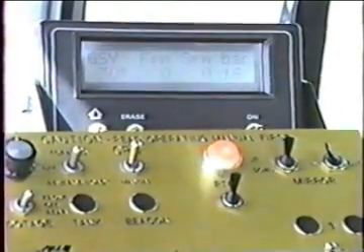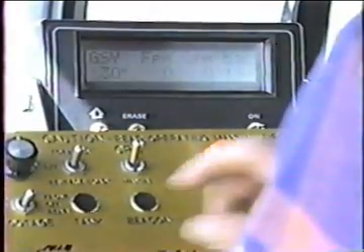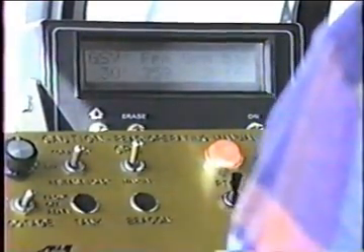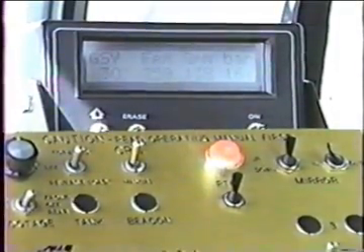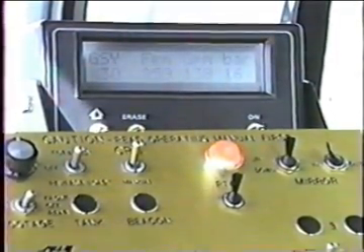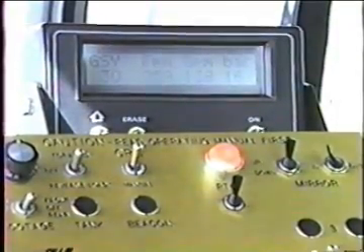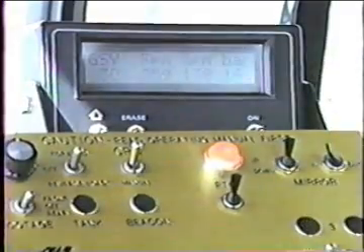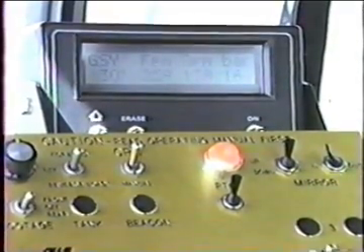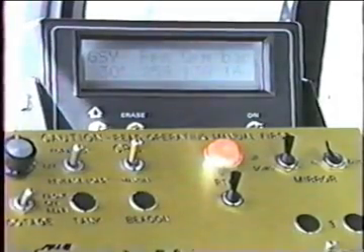As we're spreading, traveling again now, we're back at 300 feet a minute. I'm slowed down a little bit. I'm going to speed us up a little here. You can see 2 little tick marks over on the side of the bar. Those 2 tick marks indicate that at the speed we are operating, we should be using number 2 spray nozzles.